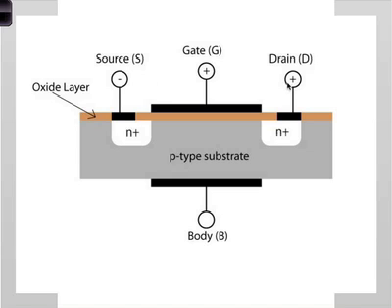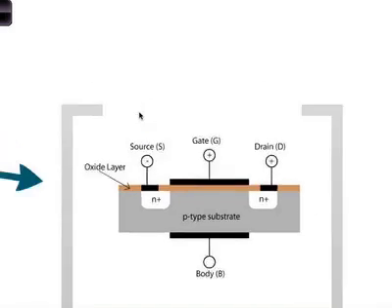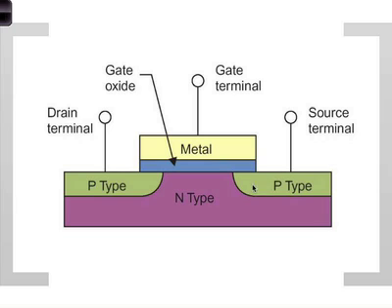From the drain to source perspective, there is no reversal of sign. So now we are only talking about the gate control, right? But the input-output voltage, they are the same. Current flows from drain to source. In the previous one also, current flows from drain to source. It's just drawn the other way, but it's exactly the same, right? I can draw it the other way. Okay. So there is no sign reversal for the input-output characteristics, but there is a sign reversal for the transfer characteristics, which we will talk about.